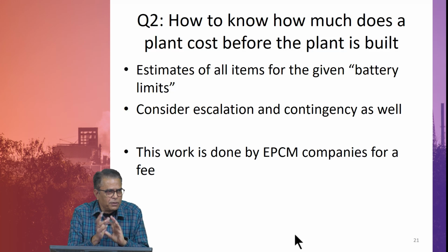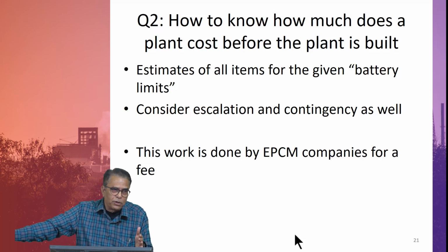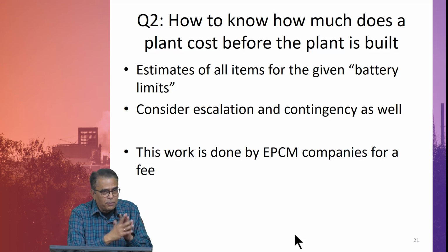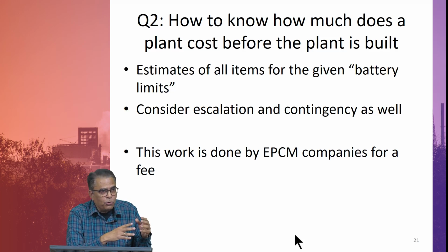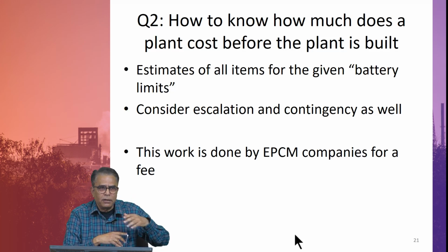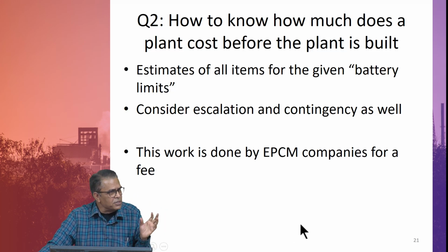So, you will have to provide for something unknown, plus for known items your costs are today's cost or next 3 months cost, but the plant is likely to be built over a period of time. Accordingly, you have to build in some escalation, and this itself is a great art engineers do. In fact, if you read Chemical Engineering magazine, they come with realistic data of how things have moved for every class of equipment, valves, pipes, lined vessels, fired heaters, insulation material, the works. So, there is some huge amount of database that has been built up by the profession.